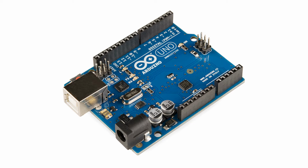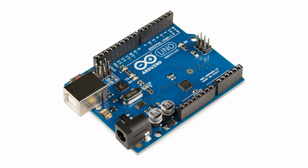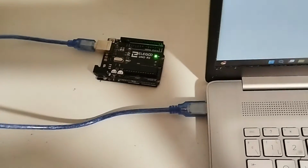But to do that, you're gonna need to know what each thing on the board does. So whatever you want to try with an Arduino, you do it through these pins. We're gonna ignore most of them for now. The important ones are these labeled from 0 to 13, which are the ones you can control, the GND pin, which stands for ground, basically negative, and the 5-volt pin, or just the positive. So now plug your Arduino into your computer through the USB cable.